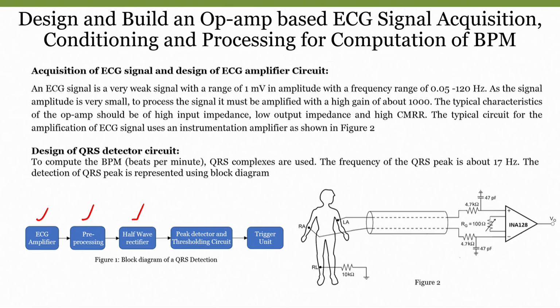Half wave rectification using op amps. If you remember, in the case of any rectification, the first and important active element that we take is nothing but our diodes. Diode plays a major role. Diode plays an active role even in our filtering from AC to DC. So, one step is our rectification, where by using diodes we will convert our AC signal into pulsating DC, right. The problem with a simple diode is impedance matching.